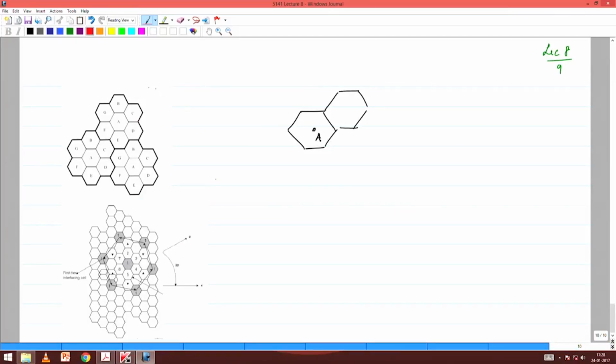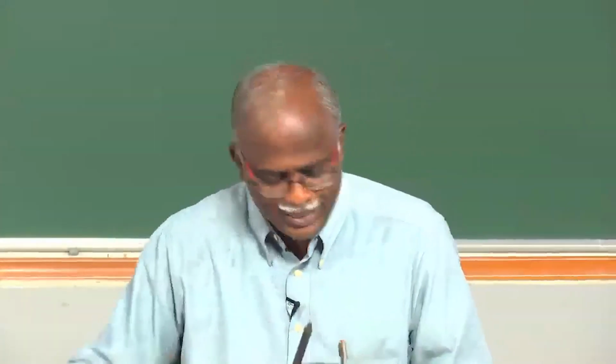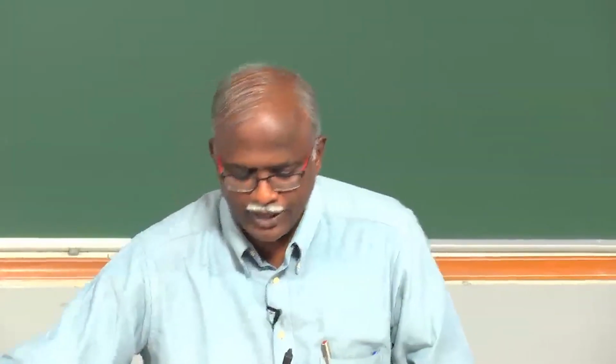So keep in mind, we are going to worry only about co-channel interference, which is going to come from any other cell that is marked A. They are not near you, and this hexagonal geometry, which we will talk a little more about, ensures that there is sufficient separation between cells that are using the same frequency. Okay? So let us go back and complete our numerical calculation.